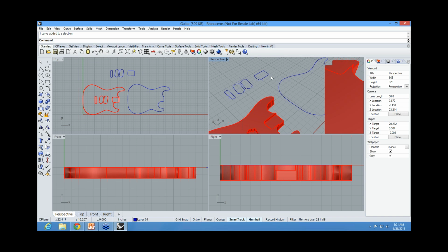We use curve Boolean for a lot of different processes. If anybody does any kind of inlay work and gets artwork from Adobe Illustrator, or gets a lot of complex artwork and needs to work on inlay patterns, curve Boolean is a great command to pick different areas of the inlay and allow you to create closed outlines to cut the different inlay materials.